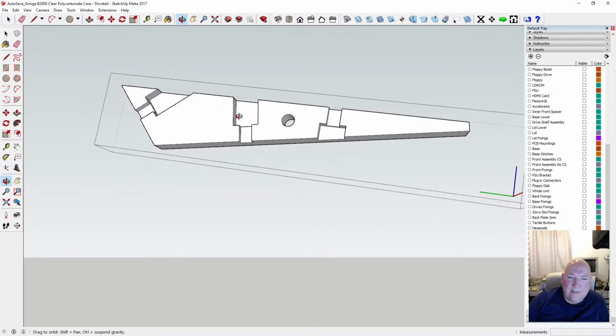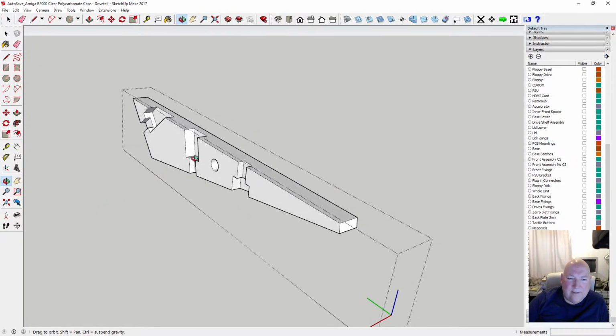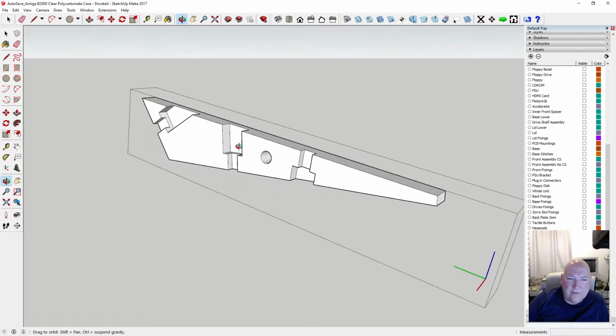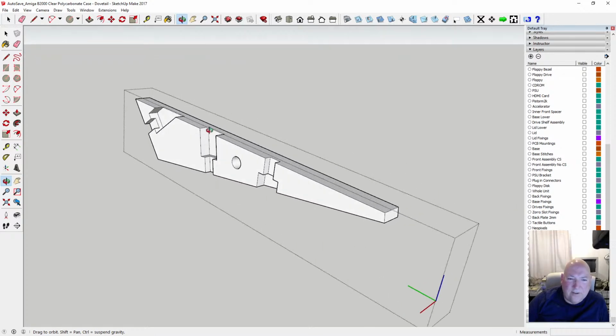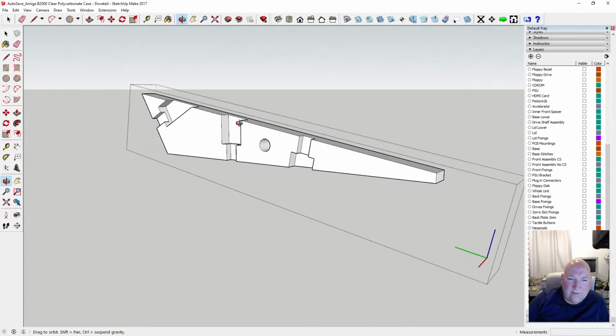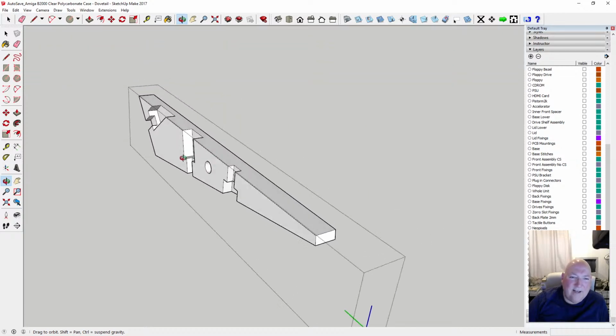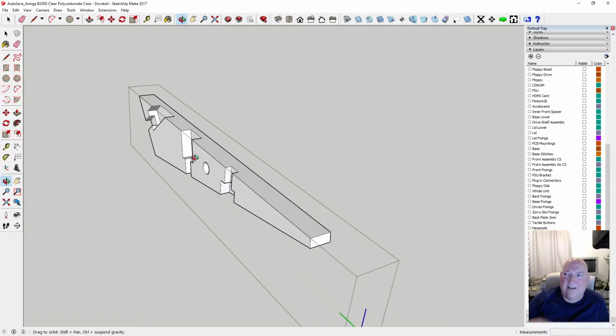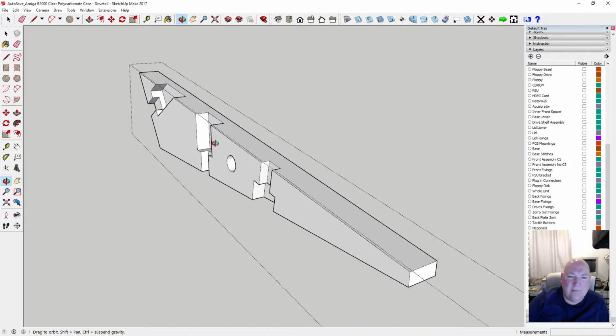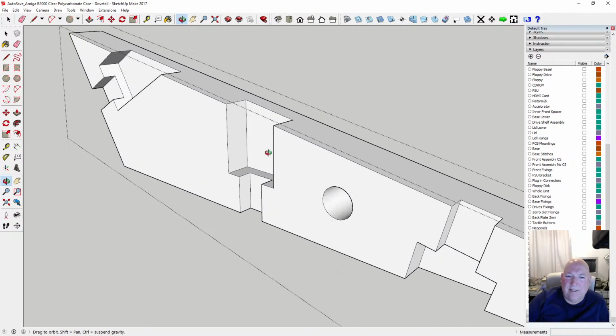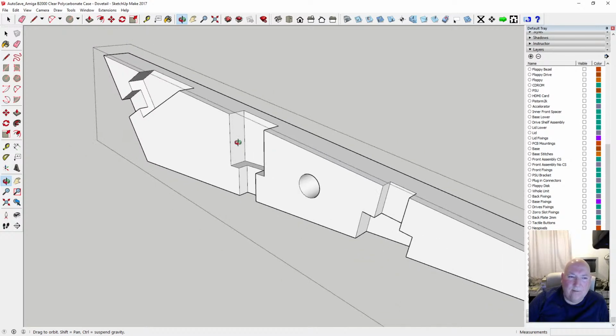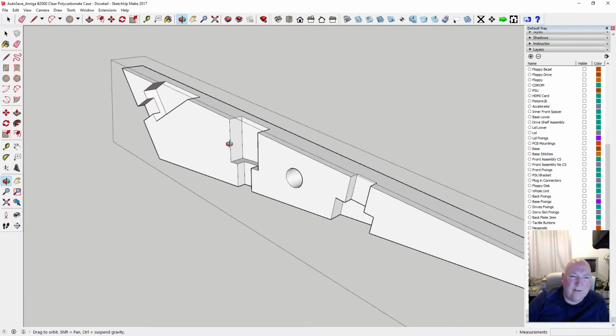And because that's milled halfway through, I've basically taken the strength away from it, all the way through there. If you put enough stress on it, I don't know if it's cast acrylic or extruded. I think it's extruded acrylic, clear acrylic. And it's brittle. It will crack. You can snap it in your fingers if you're not careful.